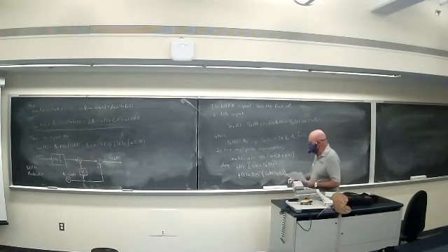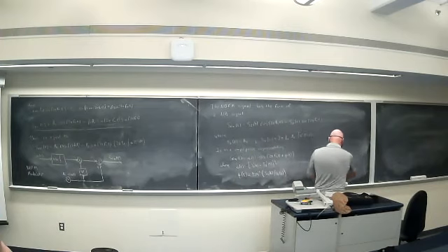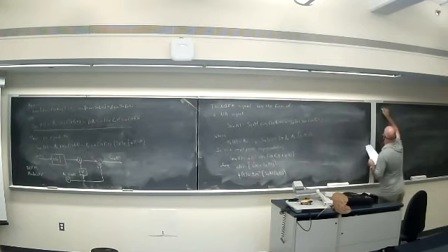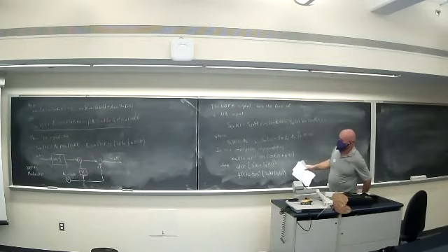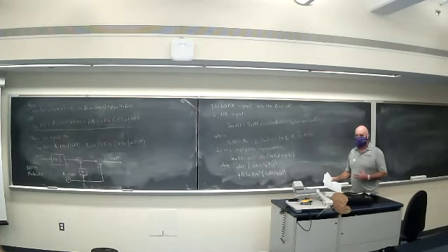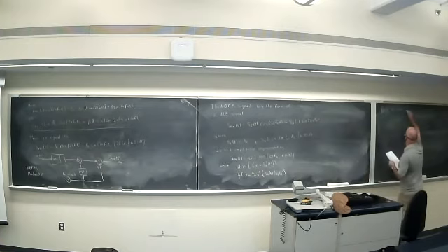Back to tone modulation. Now, I've said that FM doesn't actually have this amplitude variation, but this narrowband FM generated by that system, which is not true FM actually, because it's based on this approximation that we made, does have amplitude variation. Okay. Back to tone modulation.